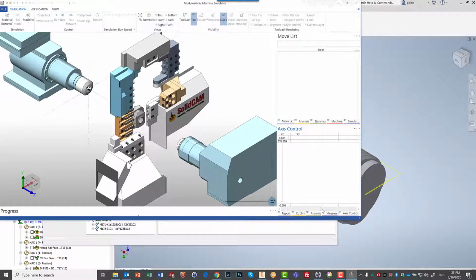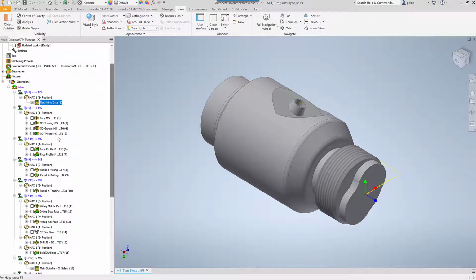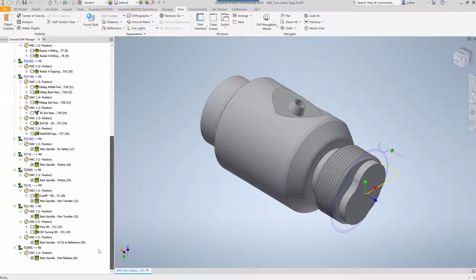And in certain particular cases, we even have a B-axis, as shown for this area over here, by moving this as well. So you can see this is a pretty complex machine that is completely controlled within InventorCAM. If we take a quick look at our operations, you'll see we have all different types of operations, whether it be turning operations to work on the face and actual turning operations to work around the part itself. We also have milling operations of all different types and working also on both sides. All of this is done as if you were working on a regular machine.